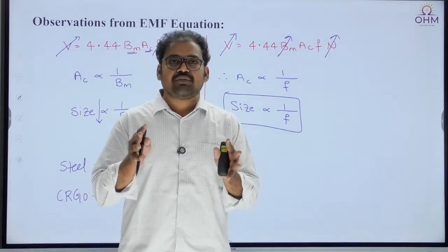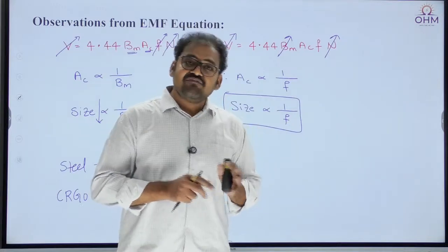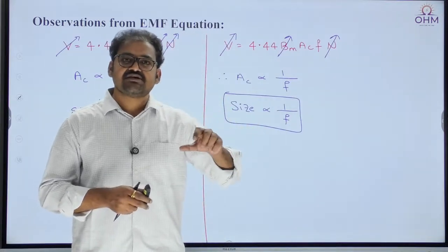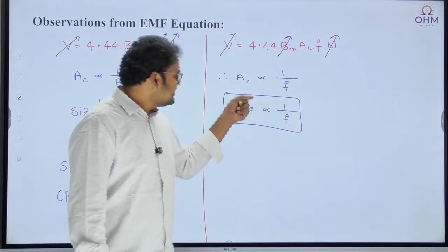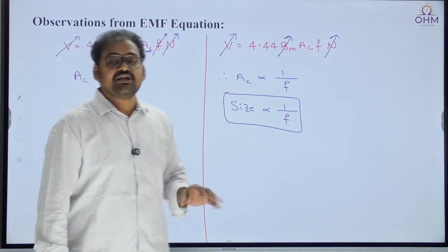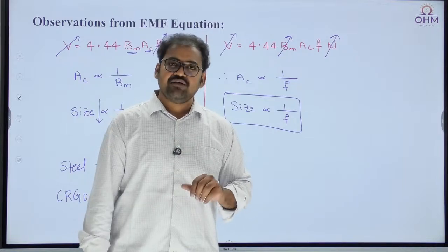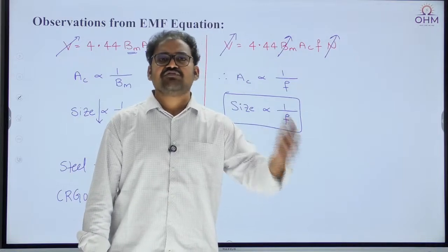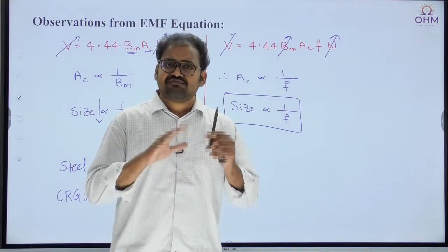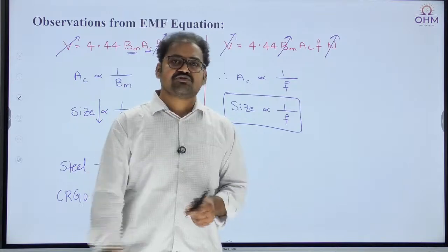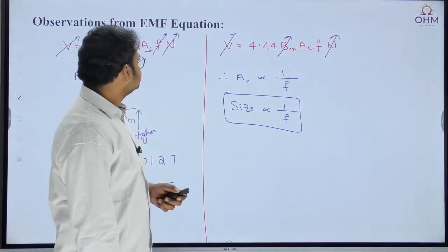Suppose I wanted to compare a 50 Hz transformer with a 60 Hz transformer, obviously which transformer will have less size? The transformer which is operating at 60 Hz. Because the frequency is high, the size will be less. But in India, the entire power system will be operated at what frequency? 50 Hz only. Of course, for audio frequencies, radio frequencies, or power electronic circuits, the frequency may be different. The frequency will definitely impact the size of the transformer. Yes, this is another important observation.